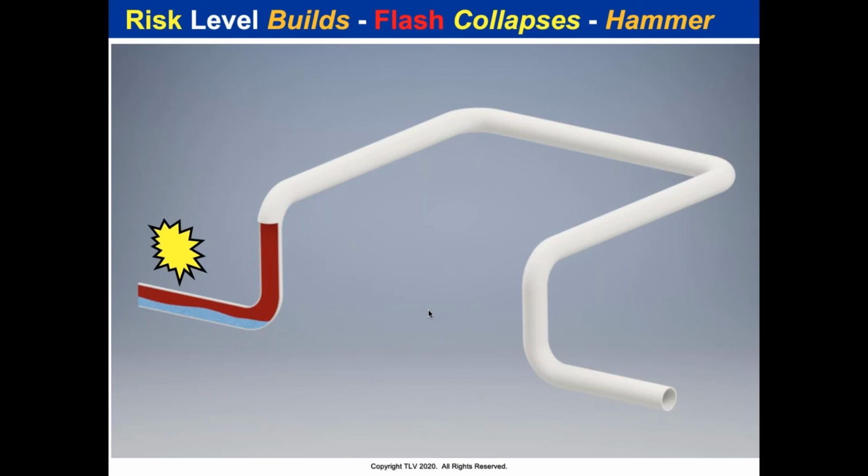So if you have a long distance, like there was a place in Africa that had 500 feet difference, 160, 170 meters, something like that, they were getting sloshing back and forth in that line with the steam pockets collapsing. And it was creating a lot of hammer. It was at a little more like 10, 11 bar system. So they were actually blowing valves off the line. Can you imagine? They're blowing valves 10, 15 meters off the line.